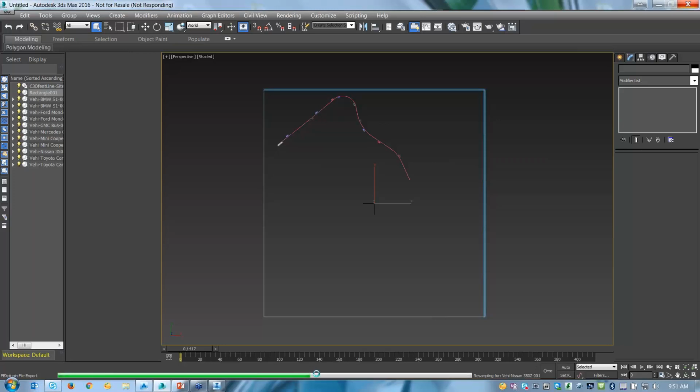So the other thing to note, and this is something that we came across fairly recently. Somewhere, and this is either in 3D Studio Max converting to the DAE, or this happens in InfraWorks importing the DAE file, the data gets skewed, and I don't mean like a horizontal or vertical rotation.